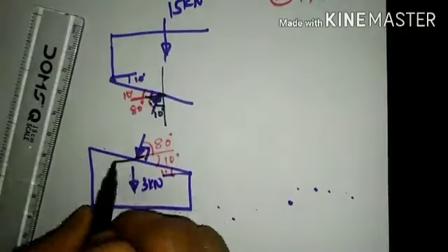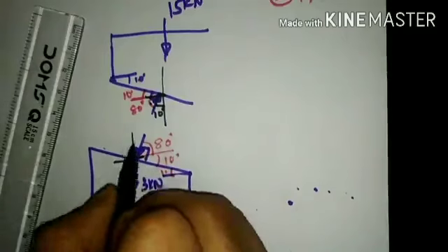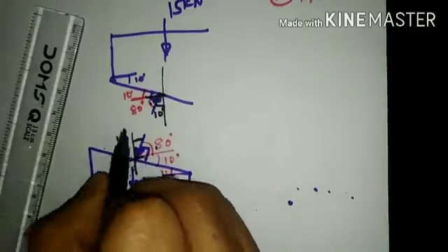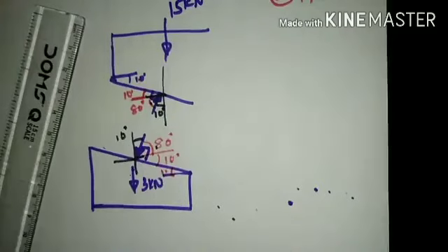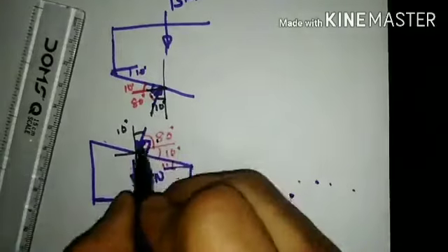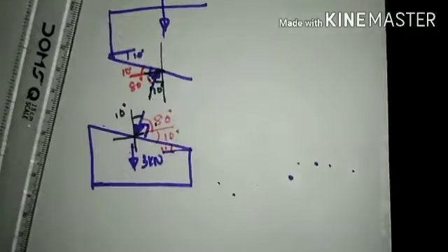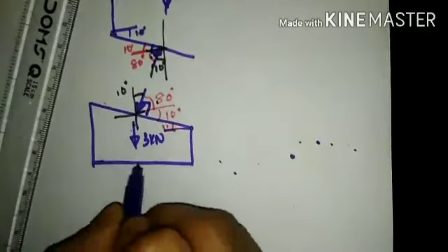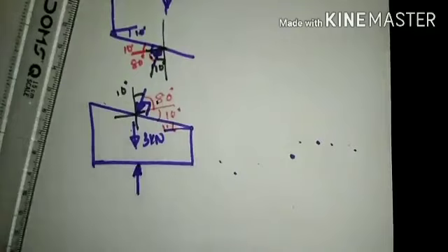Likewise, if I extend this particular x-axis line and y-axis line, if this is 80 degrees, this inclination shall be 10 degrees at this particular phase. So these are nothing but the inclinations of the normal reaction force component at the inclined phases. Likewise, the normal reaction force component at the ground level here: as the surface is horizontal, the normal reaction will be in the vertical direction.